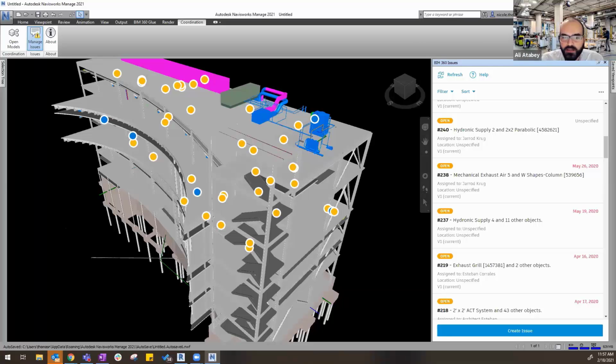Yeah, one thing to point out, and thanks for bringing this up, Nicole. It's important. I didn't get a chance to talk about it, but the issues plugin for Revit at the moment only works for 3D elements or issues that are created in a 3D view. So that adds a little bit of limitation when it comes to functionality. So I know there are a couple questions about Navisworks and clash, taking that and viewing that in Revit. I haven't personally tested that out yet, but if it's 3D, it should work. But we might have to get back to you on that, on the specifics.